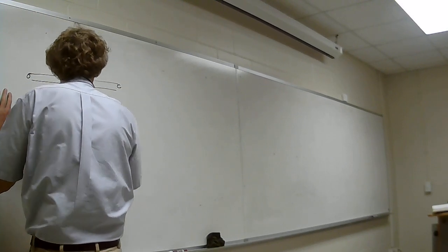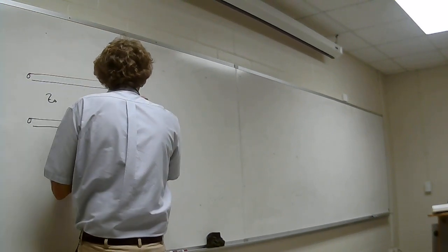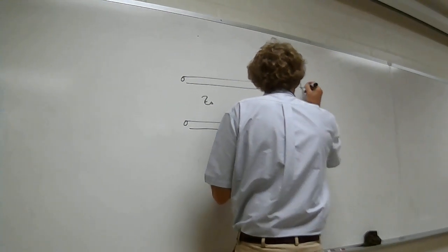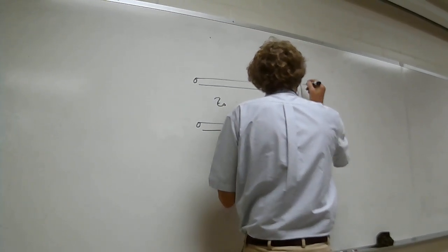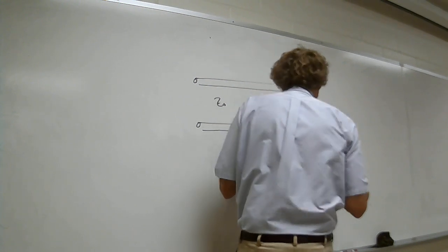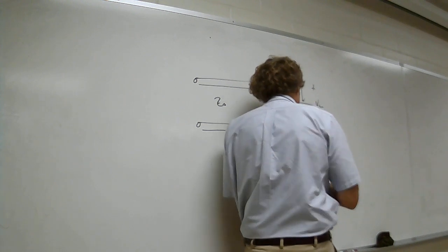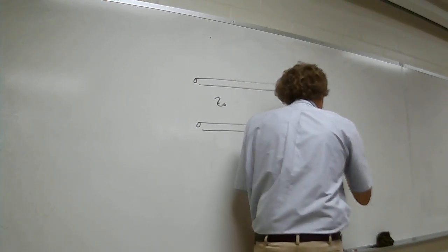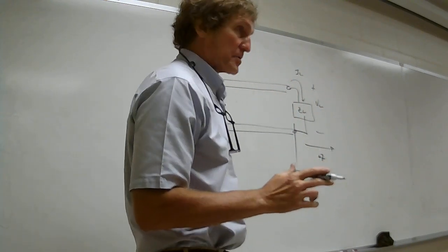This transmission line has some characteristic impedance Z0, and now we put a load on it, some Z load. And it's going to develop a voltage here, V load, and there'll be a current here, I load, as such. Almost always, for simplicity, they're going to assume this occurs at z equals 0. z will be in this direction, z plus. Y'all follow me? They do it just for simplicity.